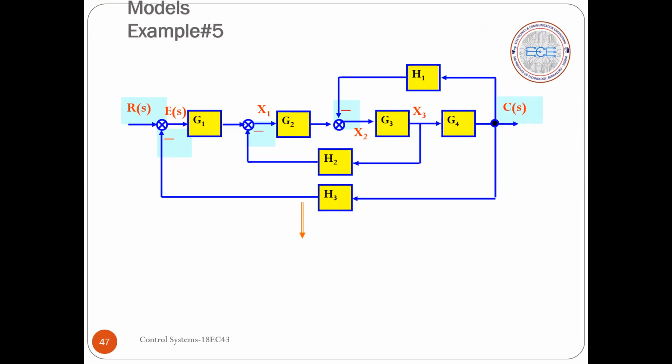In the last video, we were discussing signal flow graph, how to arrive at the transfer function using Mason's gain formula. In this lecture, what we will be learning is how to draw a signal flow graph from a given block diagram. So here we have a block diagram and we have to now write the signal flow graph. Once we have a signal flow graph, then we apply Mason's gain formula and we will fill up all the variables which we have to find out or which we have to use in that equation. We will substitute and we'll get the transfer function.